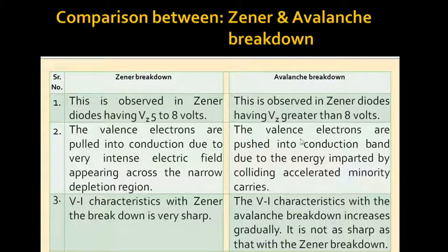First of all, one should remember that in avalanche breakdown, minority charge carriers become dominating. The minority charge carriers become highly accelerated by the high potential field, and therefore they are sufficiently energized and collide with many other carriers.